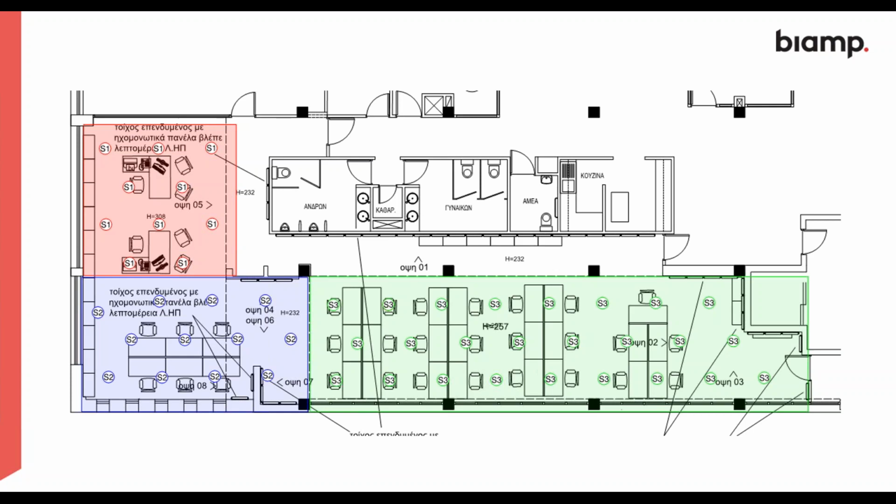If the ceiling is metal, does it affect sound masking? It makes no difference what the ceiling is at all, because we are aiming the sound down into the direct field. The difference that you will find with a metal ceiling is that when you come to tune it, you might need to tune it slightly differently, because the performance of the metal will be different from a mineral tile.